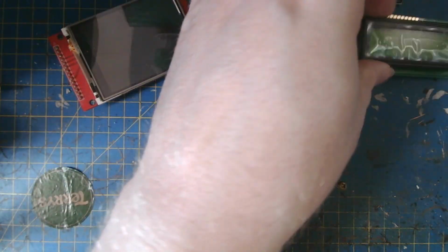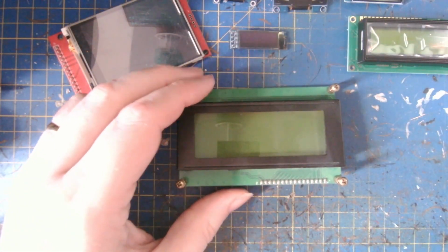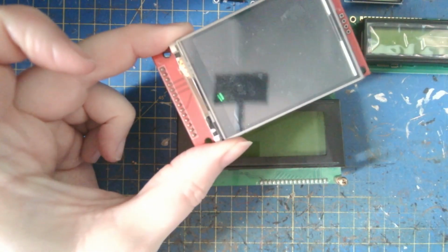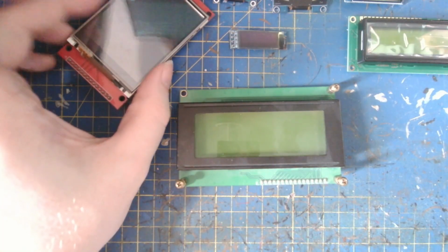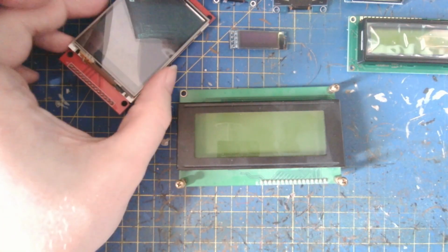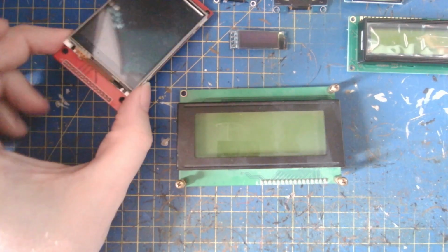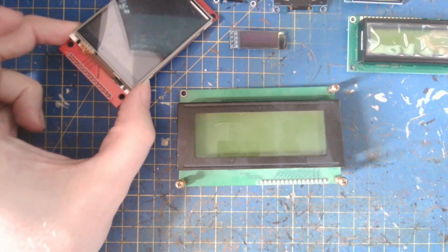That's basically that there. You then have serial interfaces in another way. You can have the serial peripheral interface. This is SPI on here. Here you have 2 data lines. One is called MISO, which is master in, slave out. Not particularly politically correct terminology, but that's the way this thing is written. The other one is master out, slave in, so MOSI.